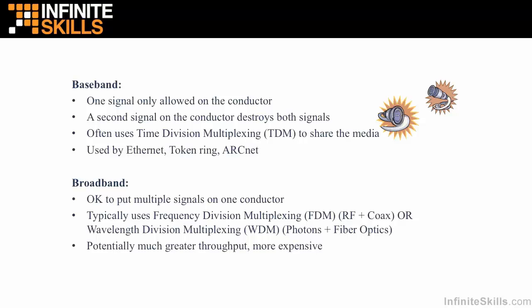Typically, this is a radio frequency, which is electromagnetic waves, a radio frequency wave across a coaxial cable. And this allows for one signal to propagate at, let's say, 10 megahertz, and I can send a second signal, let's say 13 megahertz, and a third signal at 17 megahertz, and a fourth signal at 19.2 megahertz, and I use simply a different frequency for each transmitting station, and of course the destination must be tuned to that same frequency.